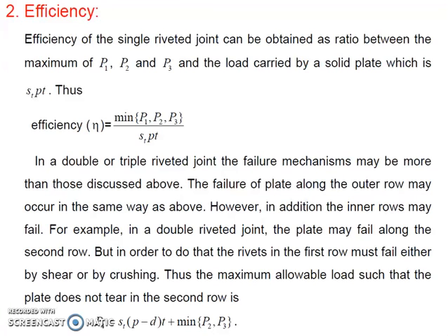And therefore, this efficiency considers the minimum of the three failure types, divided by the shearing stress multiplied by P, the pitch, and T, the thickness of the plate.